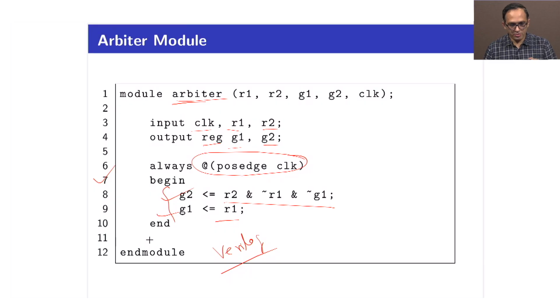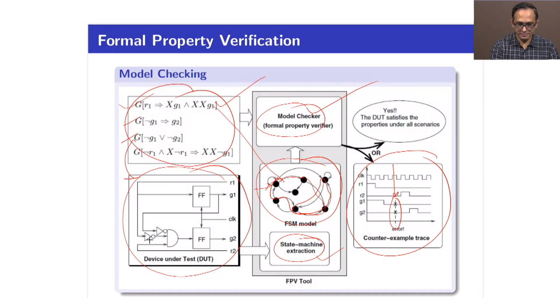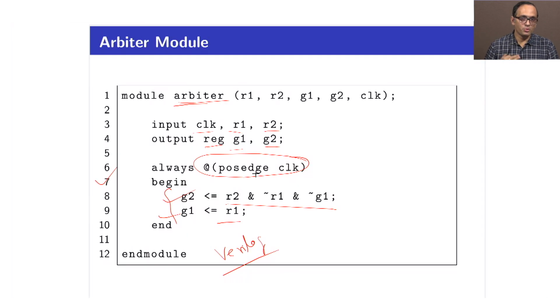As I mentioned, the first job is to identify the FSM. How do we identify the FSM from this implementation? That is the first question. What is a finite state machine? You think of it as having many states and state transitions. What does a state mean? It is the current value of your sequential logic or sequential elements. What are the sequential elements in your design?